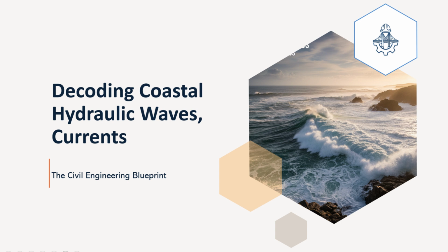This wave-induced pressure varies sinusoidally with the wave's passage. At a fixed depth, z, it reaches a maximum positive value directly under a wave crest, adding to the hydrostatic pressure, and a maximum negative value, a suction relative to hydrostatic, under a wave trough. This oscillating pressure can exert significant fatigue forces on structures.